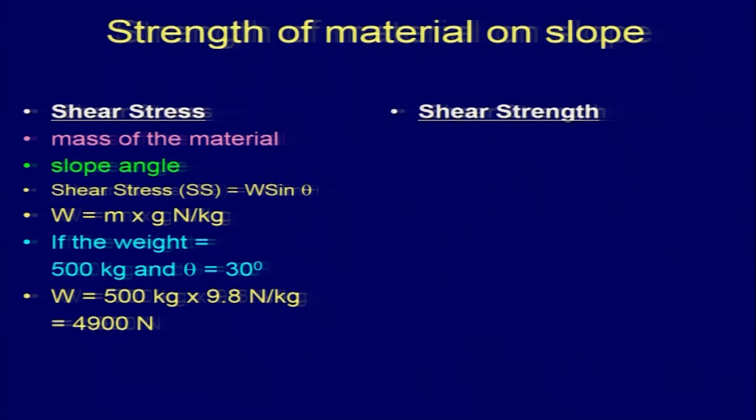So, this will give you 4,900 Newton of weight or force, and the shear stress will be 4,900 into sin 30.